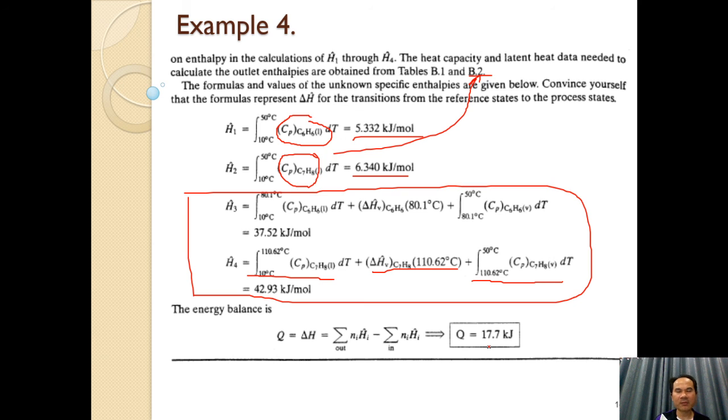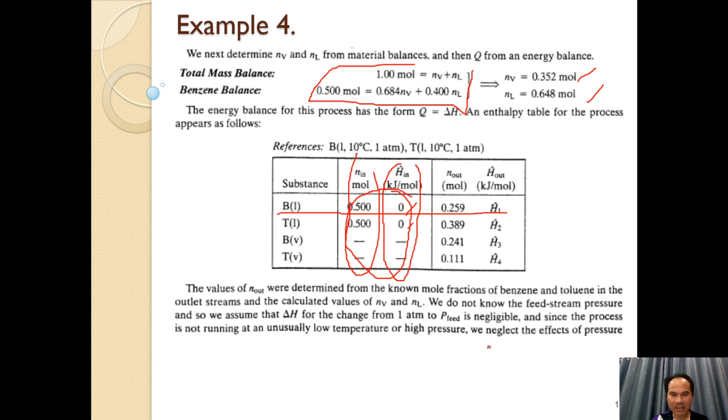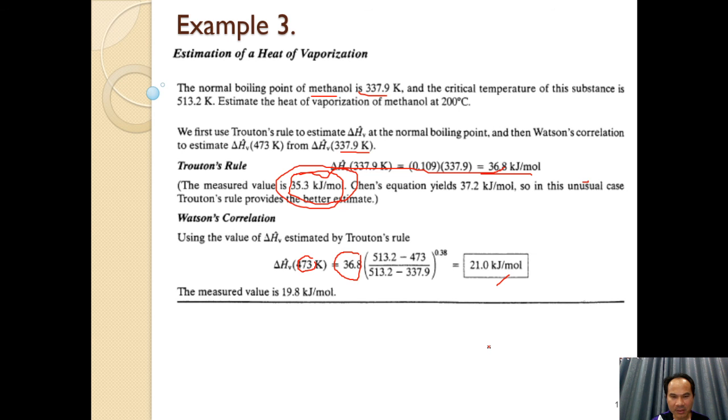In this case, when you do the enthalpy balance, you change the temperature and you change the pressure. Mostly the entropy term associated with the change in pressure is a very small value compared to the others, like in this example I showed you in the comment.